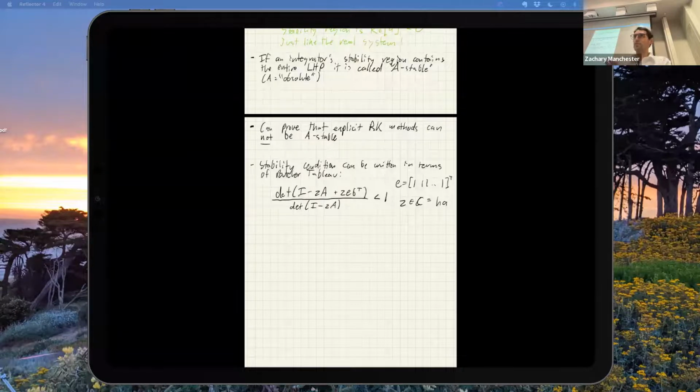So if this is stable, it is stable. If this is unstable, it's unstable. If this comes out exactly 0, that's kind of a case where it's iffy. Because this is a linearized, first order result, the place it breaks down is when the linearized term is 0, in which case the nonlinear terms start to matter, like we said before.